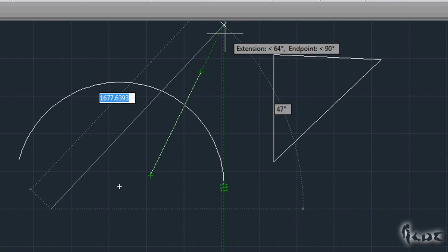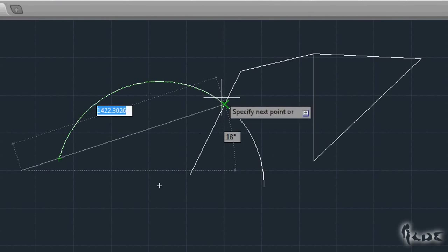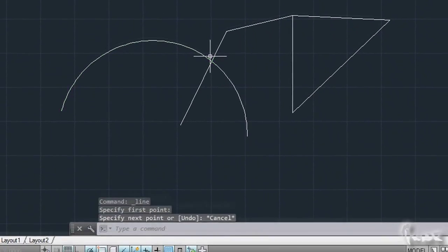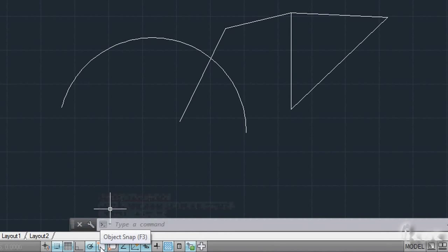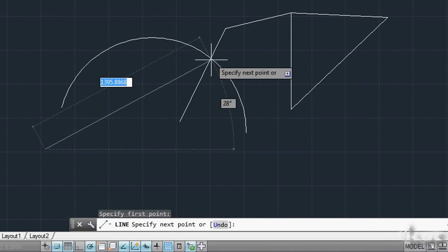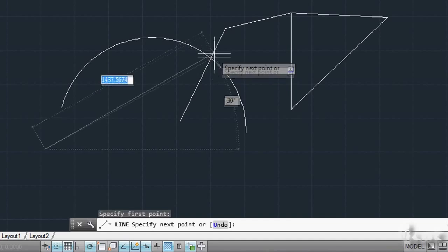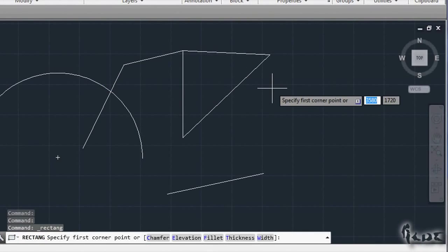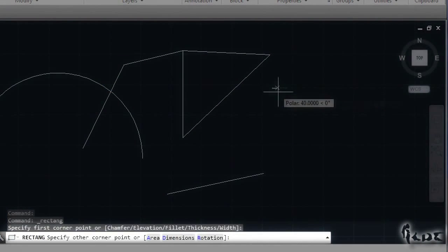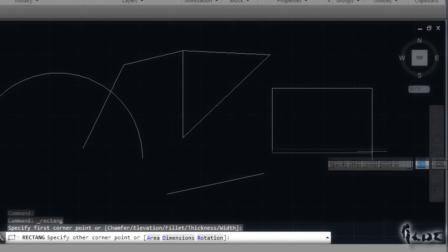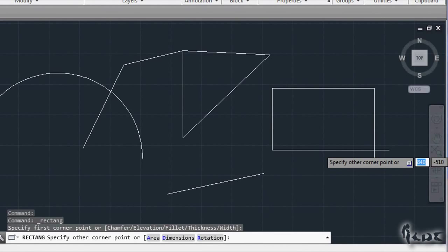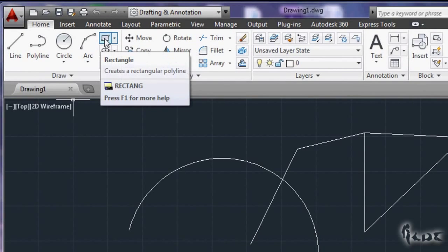By default, your pointer will snap to these green squares, making things easier. If you want to disable snapping, click on Object Snap to turn it off. This will let you move as you like. While drawing, the command line below will guide you through. Each time you draw or do anything, the command line will tell you what to do or any choices, which are indicated through brackets. Choose Rectangle.